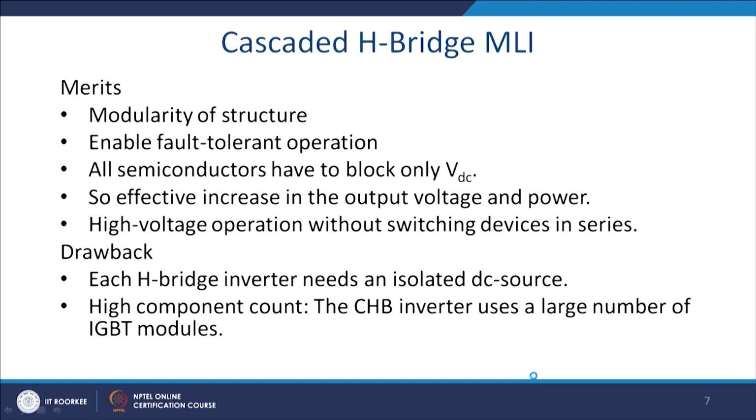So, merits: you can have such a high degree of freedom, it is modular in structure, you can add on, and it enables fault tolerant operation, because you can introduce short circuit protection for any of the devices. All semiconductors will have the same blocking capability, thus uniformity. It is so effective that it is very much retrofittable.